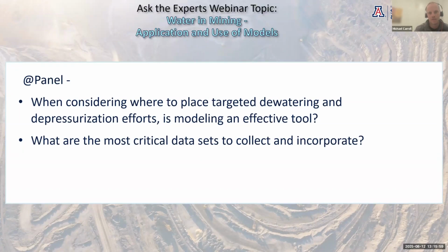However, we utilize modeling quite effectively to assist with optimizing spacing of dewatering wells. So you might still utilize site-specific data from densely spaced drilling operations to site your greatest saturated thickness, but you would utilize the model to develop your strategy and where to place the wells.